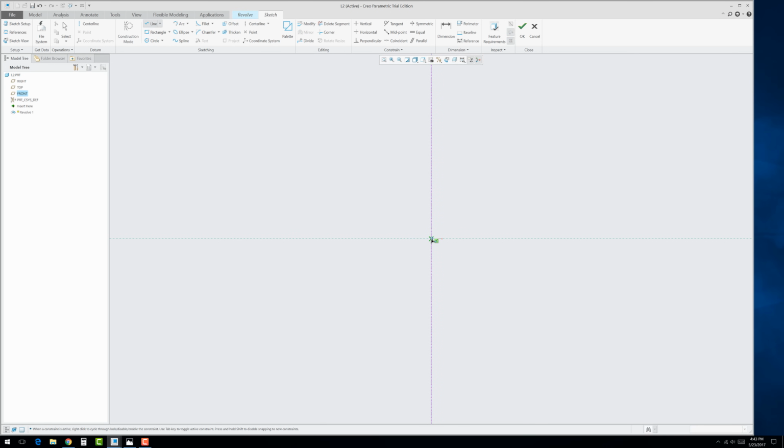Now take the line tool, draw up. The bolt is 2 inches in length, so middle click, double click, change that to 2. Now go back to the line tool, and at the bottom here, click, drag this across. You could put the chamfer in, but I'll show you the chamfer as a feature. It's a little bit easier. Drag this up. This is about 1.7, but I'm just guesstimating where it is. And then out here, it comes out a little bit, and then straight up, then middle click.